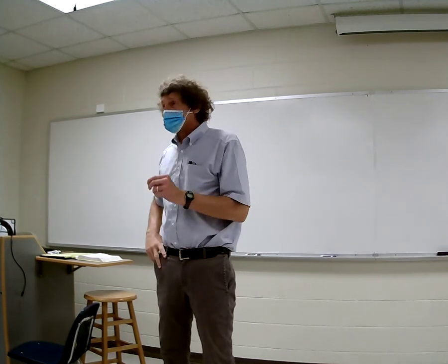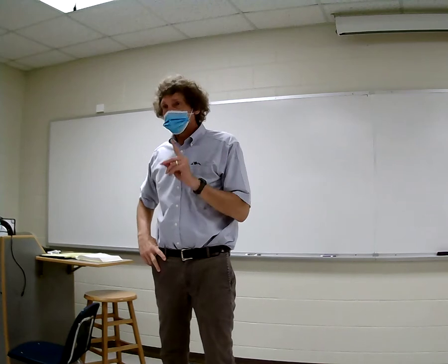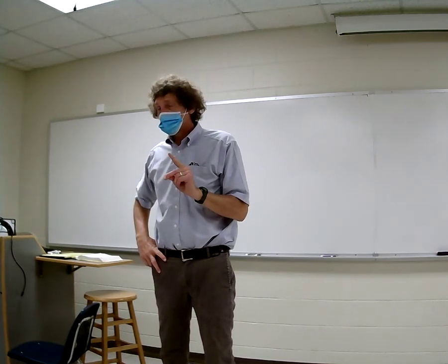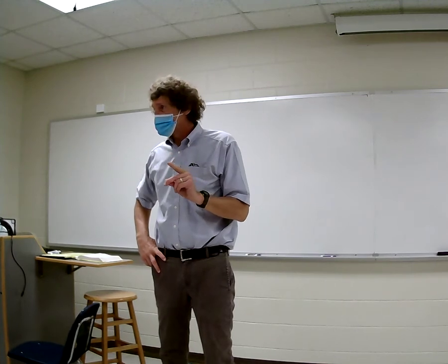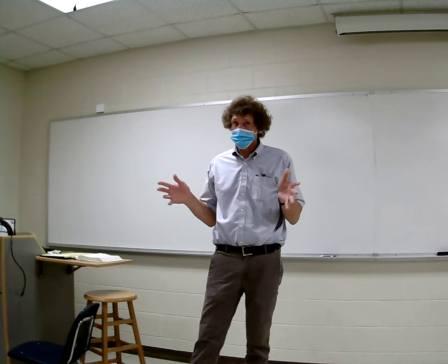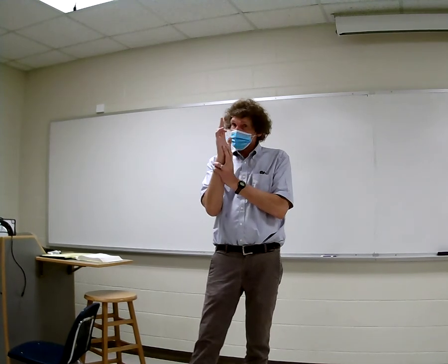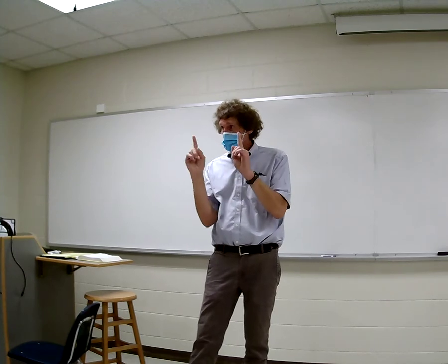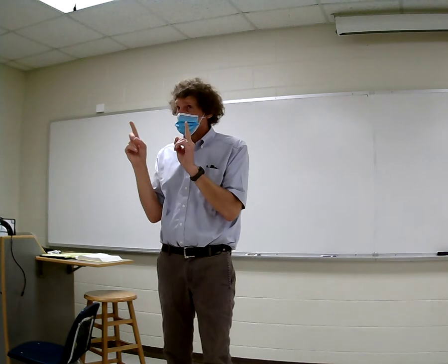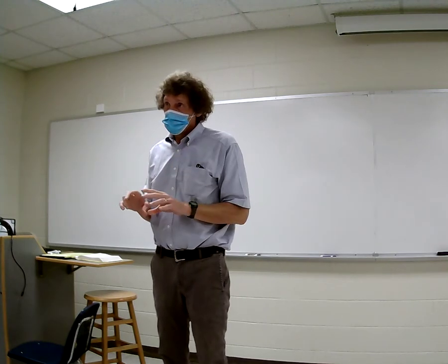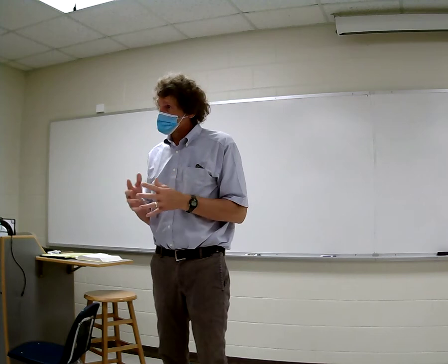I want to make one other point about this. This matching is only for a certain frequency. You follow me on this? So if you get into stuff in the real world where you have wide band systems, wide band means you're not just a little bit off the frequency. That means a fairly large modulation index, where you're going to have typically FM modulation on something, and if it's wide band, then the method I'm showing you here falls apart.